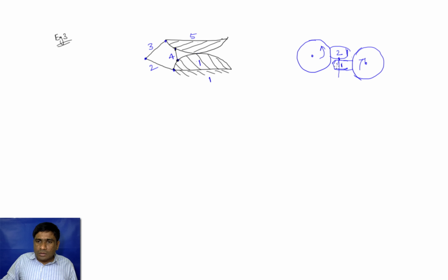When gear tooth 1 touches gear tooth 2, it not only pushes this gear in this direction, but it also slides along this line. We will see that in detail when we talk about gears and gear trains. So between a gear engagement there is one rotation, as well as a sliding between these two gears.